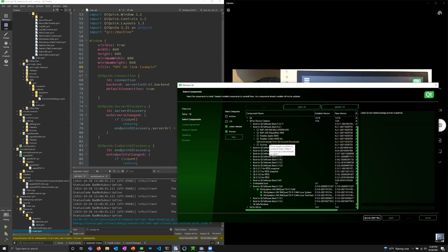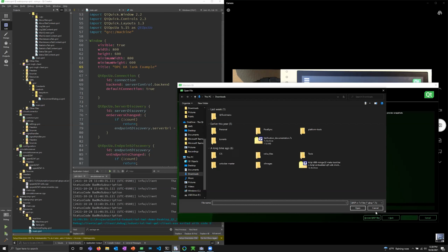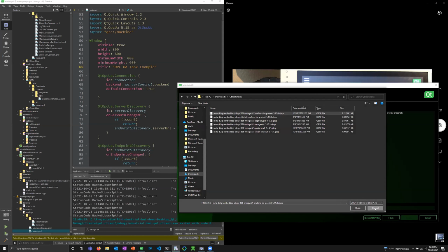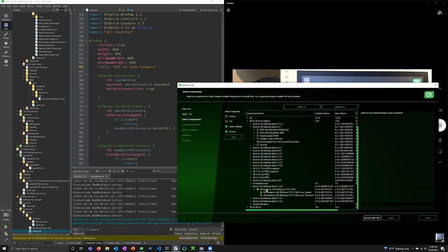There's additional QBSPs you can download from your account on our website. And in our example, I have the WINSYSTEMS built QBSP for the C444, and that is installed. To install them, when you obtain them, you download the file. It's an archive. You go to Browse QBSP and locate your QBSP file, select it and open it. That gets extracted and shows up in your installer where you can check what you need.